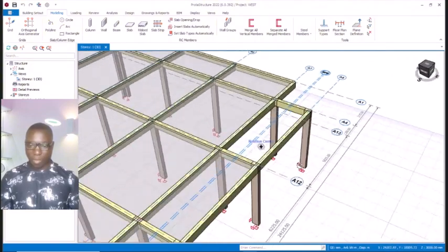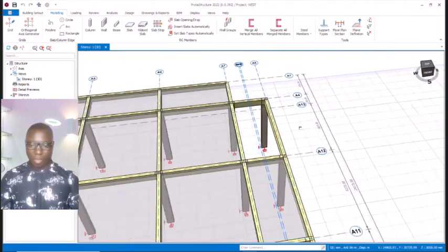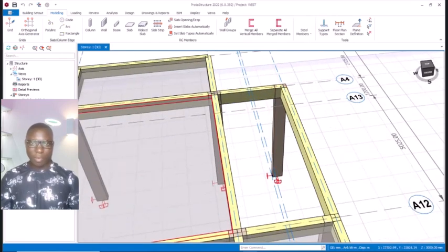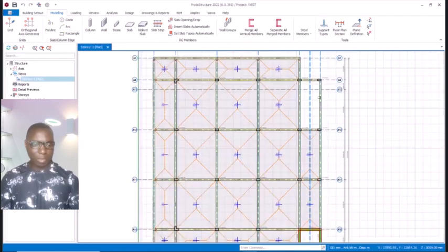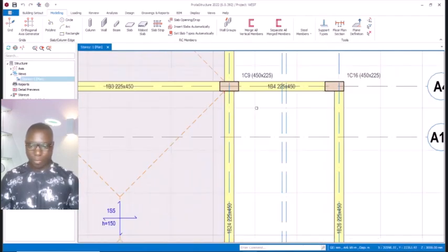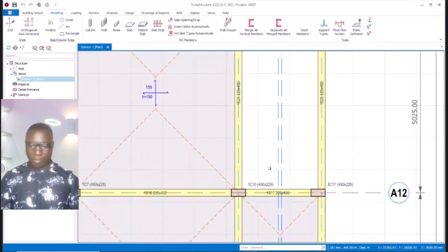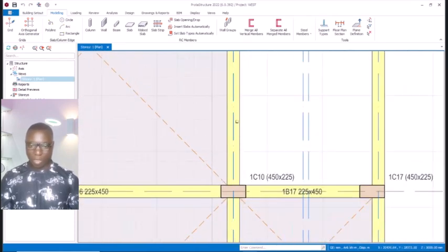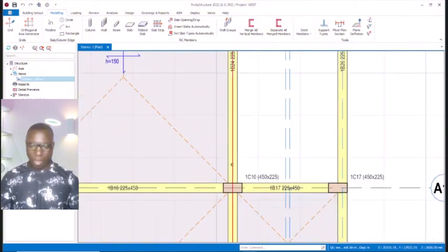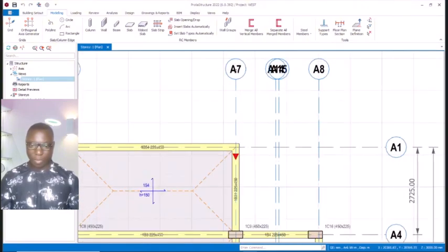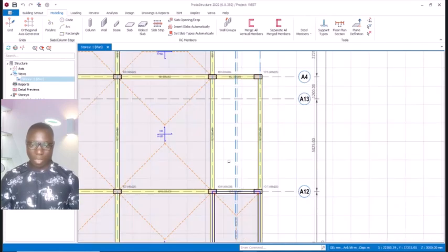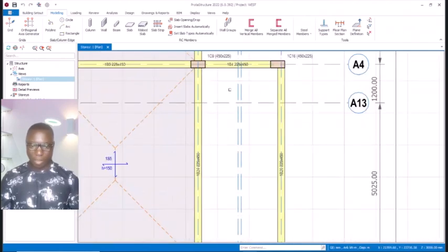So we are going to be creating the staircase at this story 1. Right, to create your staircase, what you have to do, navigate to the plan view, and then here we go. We have this, and then we have this. We want this staircase to actually run along the side of these beams, or it may be anchored to the A7 grid lines successfully. Okay, let's go by that. So what I will do is this total story height is 3 meters.